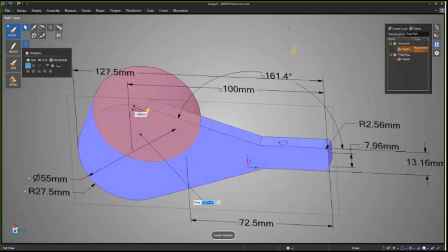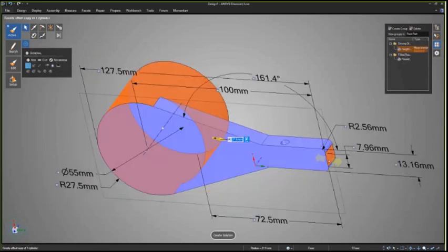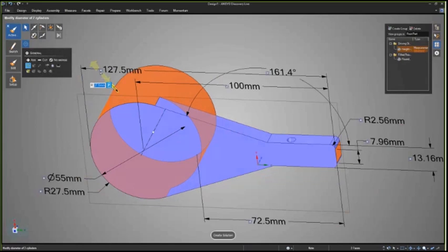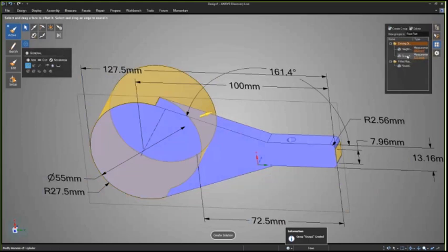But even these other ones that I did, where we pulled on, say, this cylinder and this space here, and drove it with this value here, if I hit enter, that P shows up and I can click it, and then I have, we'll just call this the length. And so I've got two parameters there.